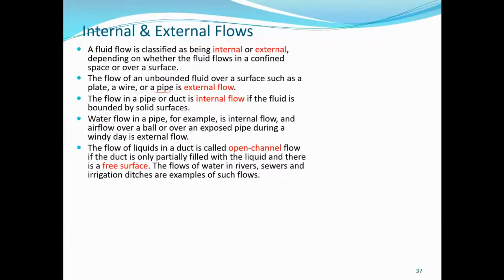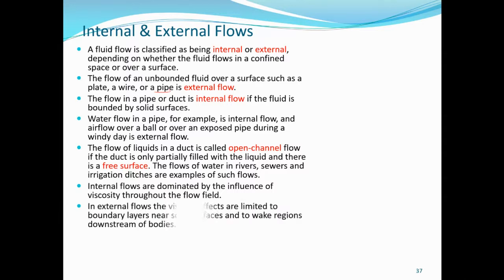The flow of liquids in a duct, that's like a pipe, is called open channel flow if the duct is only partially filled with the liquid and there is a free surface. The flows of water in rivers, sewers, and irrigation ditches are examples of open channel flow. Internal flows are dominated by the influence of viscosity throughout the flow field because the fluid is bounded completely by the boundary surface, like in a pipe flow. So you have a lot of influence of viscosity.